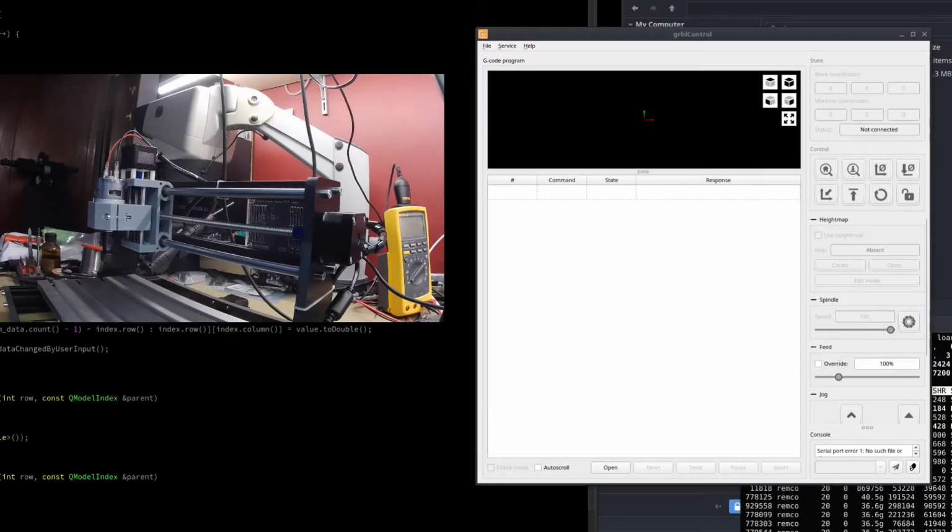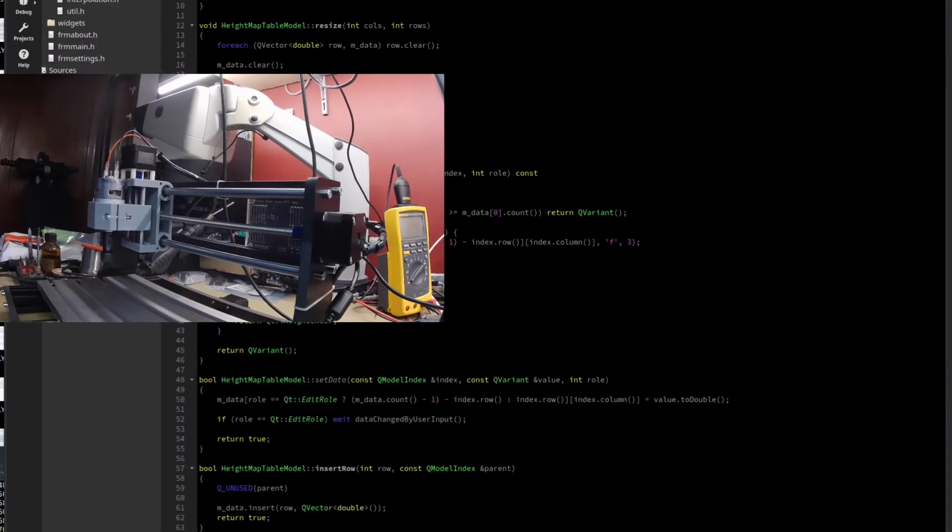Okay, so I'm on my way towards running GRBL control under Linux. There's a version you can download and it's complaining about GTK headers and being annoying. So I went to the GitHub and downloaded the code, which runs in Qt Creator. That doesn't compile right away either on my system. It's complaining about bad declarations of isnan, not a number. The only thing you have to do there is integrate a line.